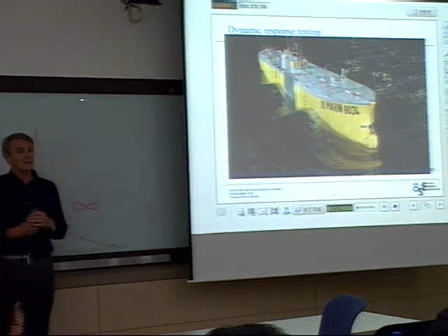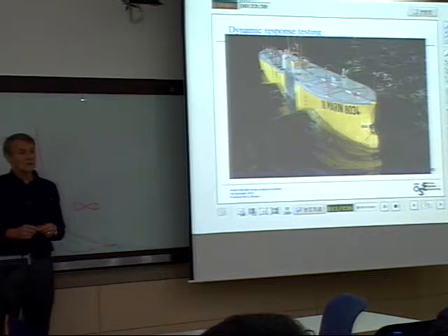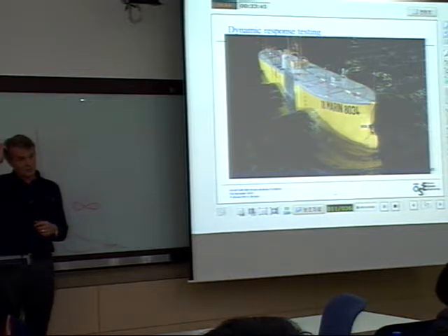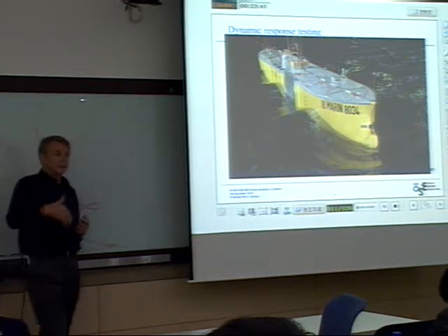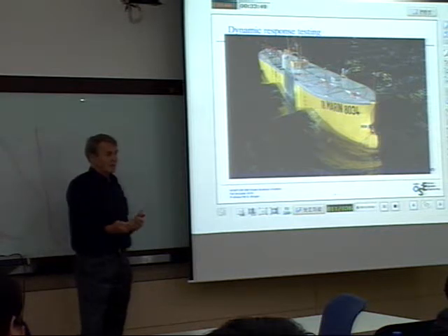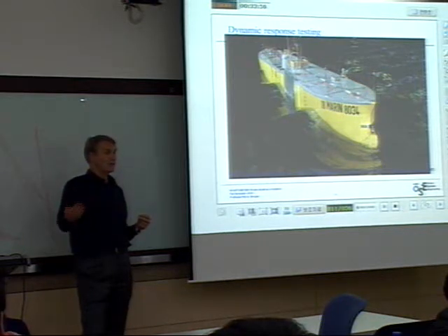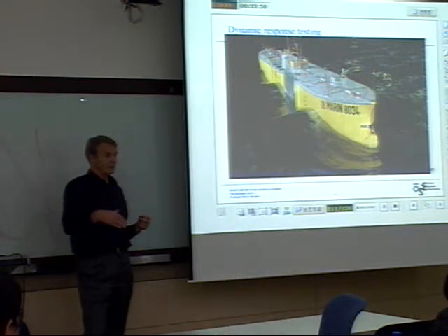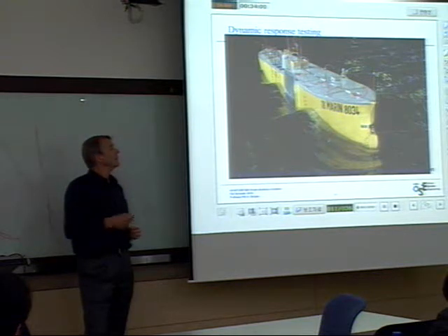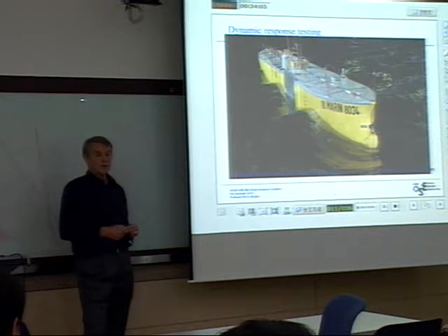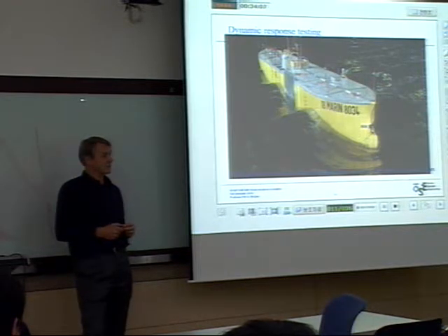And why don't you want to have fatigue problems with the FPSO? Well, it's much worse than for a ship, because a ship you take into inspection typically every fifth year. If the ship is not too old, you take it into dry dock. These FPSOs have to operate maybe 30 years without being taken to a dry dock.